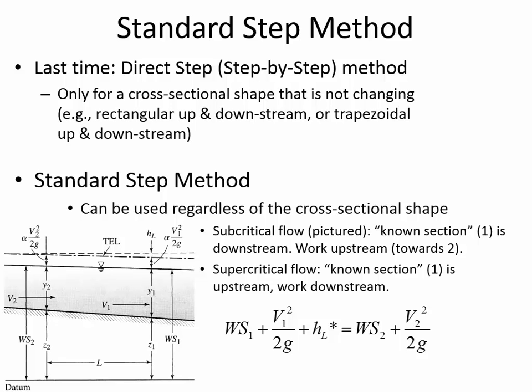This is the same diagram we looked at in a previous lecture where we saw that there are three different slopes. There was the slope of the channel bed, the slope of the water surface, and the slope of the energy grade line. And we saw that the depth was increasing, and so the velocity was changing. Now the difference here is we have some horizontal datum that we're measuring everything against. And what you can see is that we're going to be measuring what we call water surface. WS stands for water surface. And that is the measurement from the datum to the channel, so that's the Z, and then from the channel to the water surface, and that's the Y.